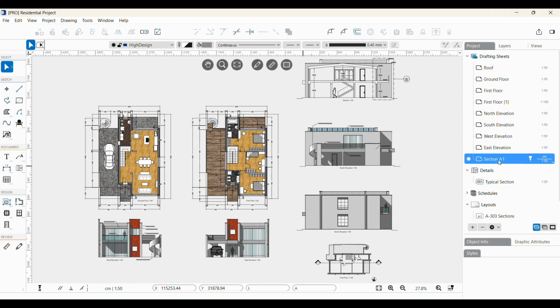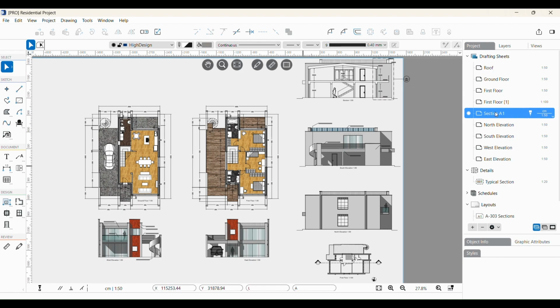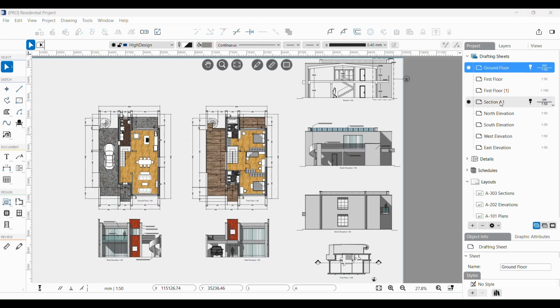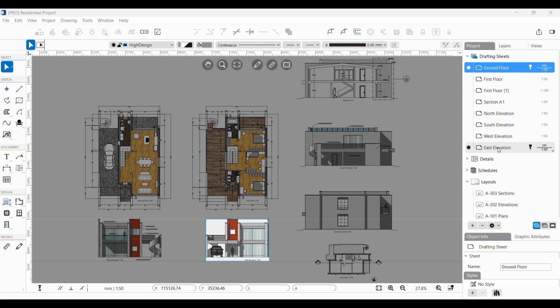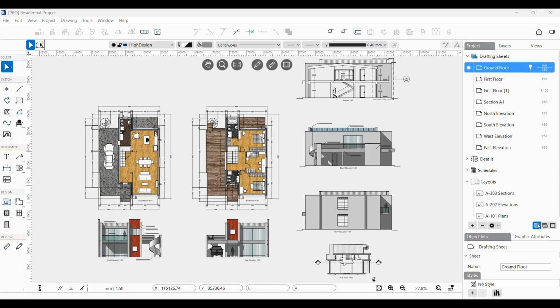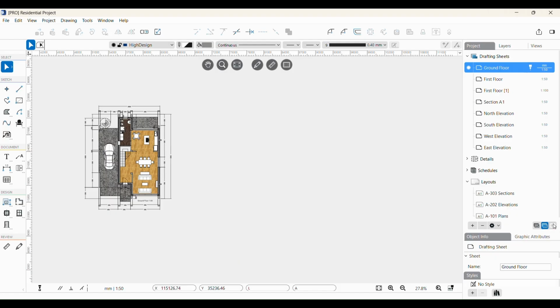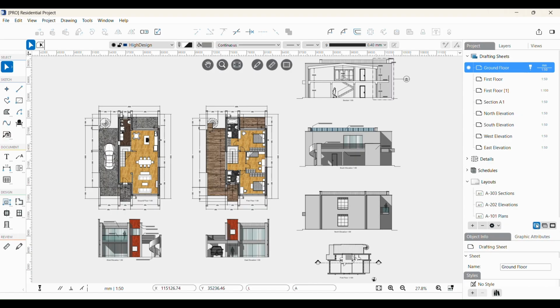To arrange a sheet, drag it to the new position. The table order corresponds to the actual display order, where the topmost visible sheet is the first item of the list. You can control how the sheets are displayed on screen by clicking the opacity button. There are 3 states: all sheets equally visible, the current sheet displayed normally and the others dimmed, or only the current sheet visible.